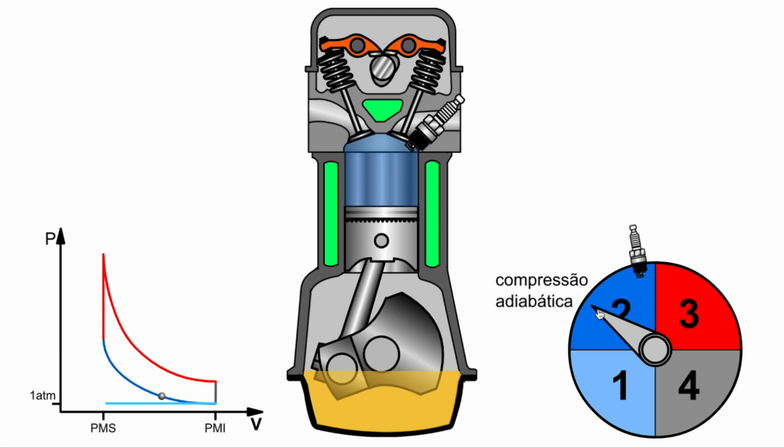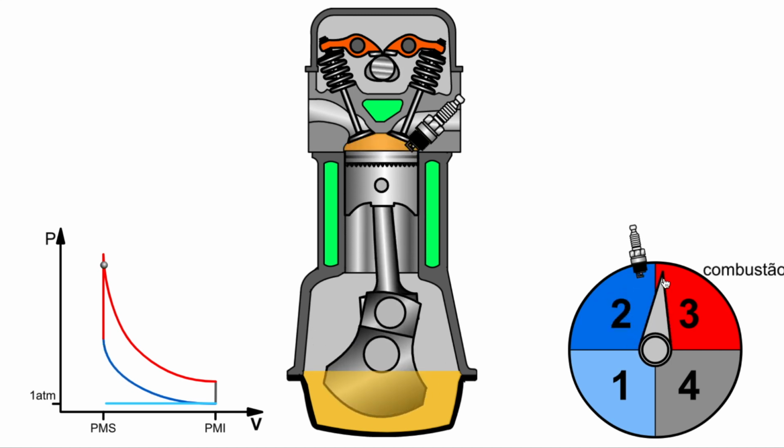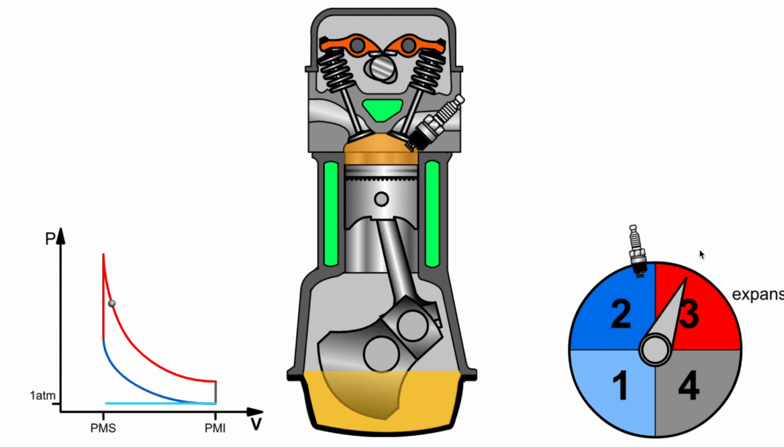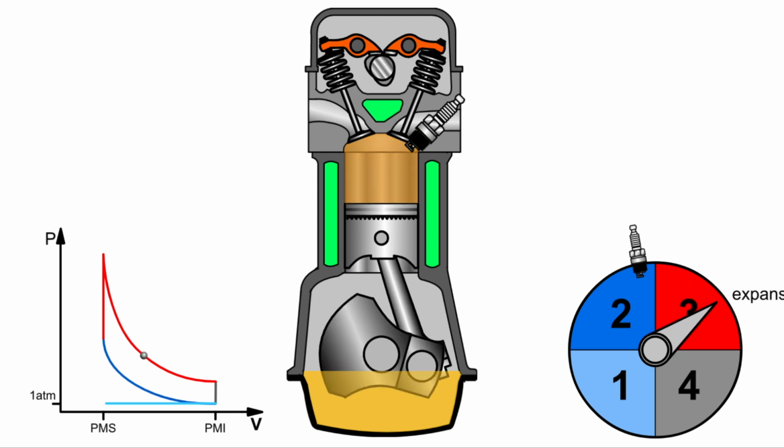So you need the spark to actually fire late to help you get the pistons turning over fast enough that the engine can keep itself going. In this scenario, having a lot of excess heat is actually good because you need the engine to get up to operating temperature quickly. So it's good that it's throwing off a lot of heat.